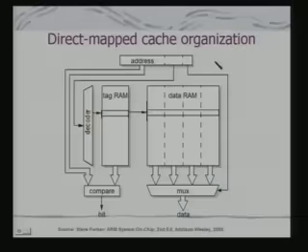So, this is an example with respect to the ARM architecture. So, you have got an address. If you see, this is the tag part, and the index part is directly being fed to the decoder to select the cache block. Then, there is a tag RAM apart from the data RAM, which contains multiple bytes, that is a block as a whole.